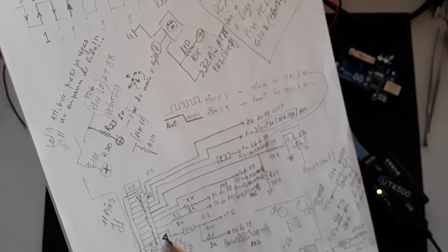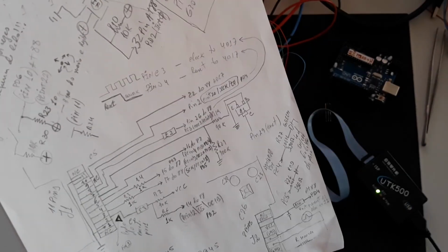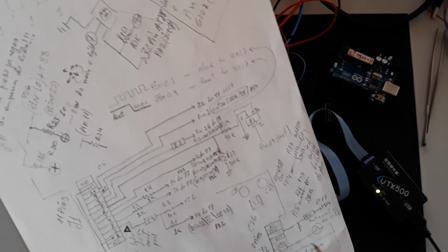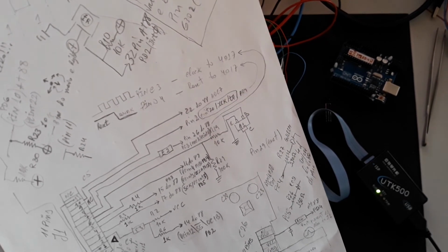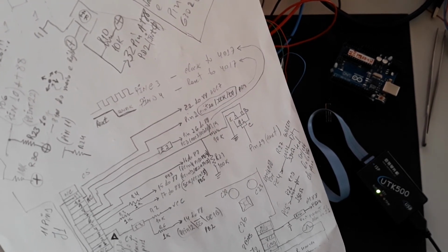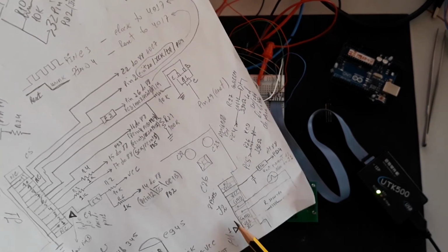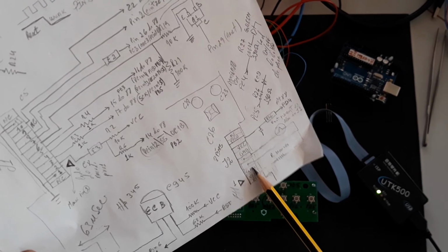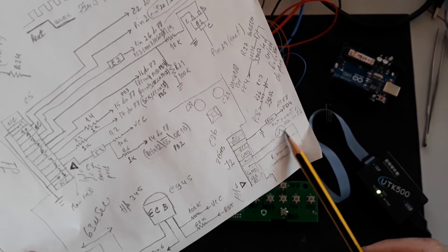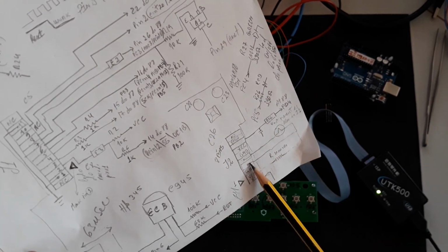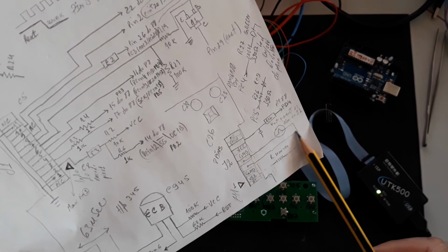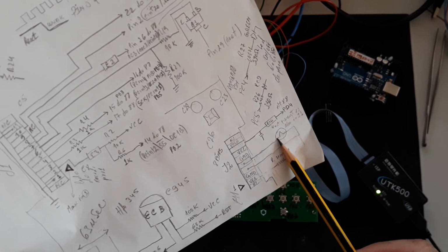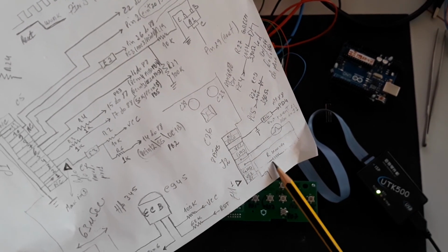Here you have the mark to point to pin 1 of the connector. Here on the board you also have the mark for the power connector, okay? In the power you have the negative 12 volts here, GND, and the filament, these 2 points. Remember, you need to make the reference of both powers, the filament and the negative 12 volts, okay?